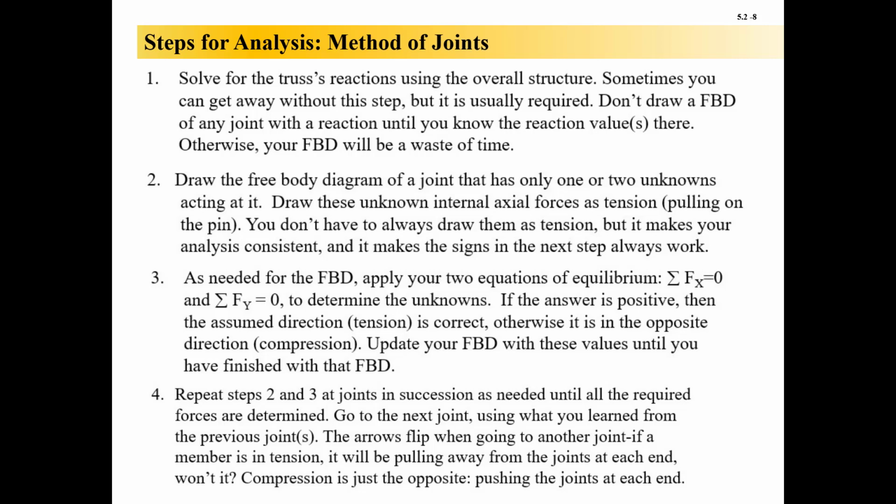So when you go to what I like to say is the quote-unquote other side of the free body, which just means the other end. Other is a very vague term because you're going to be drawing lots of free bodies, and it is kind of vague. But when you go to that other side, the arrows flip direction. You'll see that time and time again in statics, especially in trusses here and now.